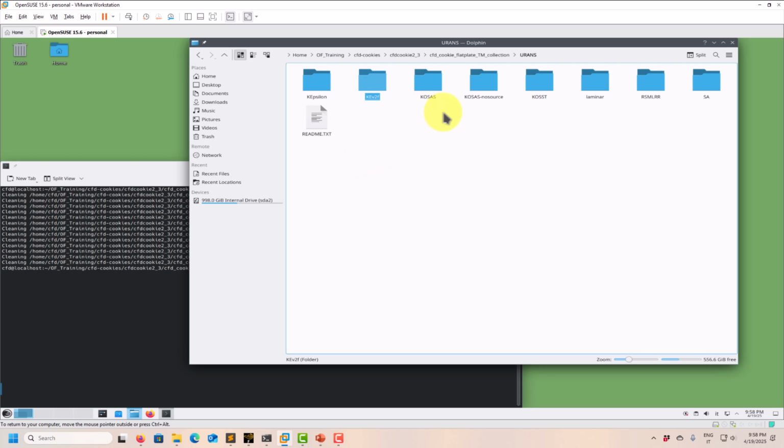So the K-omega source, we already studied this model. In this one, the no-source case, we don't have that, and we know what is happening. By the way, in all these cases, if you disable the source, you're going to get your standard steady solution. So let's go to the K-omega SST.